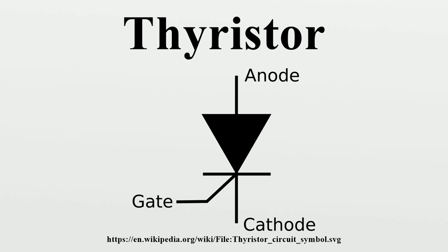A LASCR acts as a switch that turns on when exposed to light. Following light exposure, when light is absent, if the power is not removed and the polarities of the cathode and anode have not yet reversed, the LASCR is still in the on state. A light-activated TRIAC resembles a LASCR, except that it is designed for alternating currents.